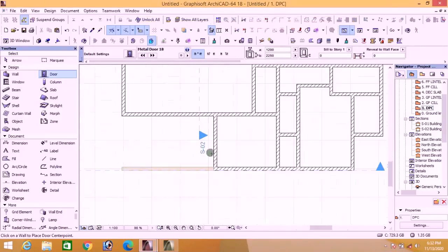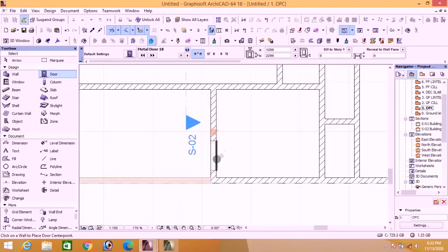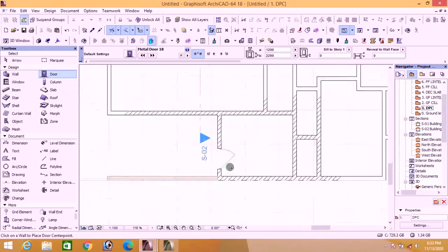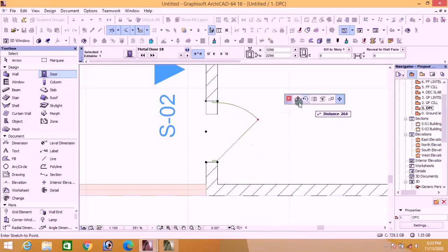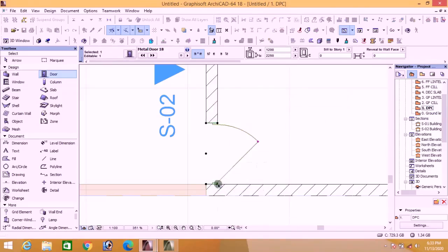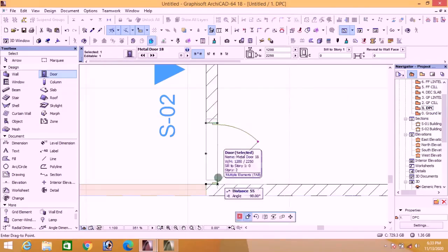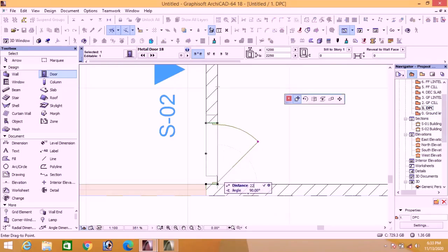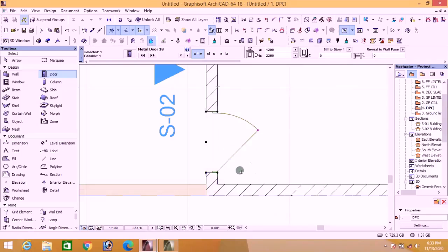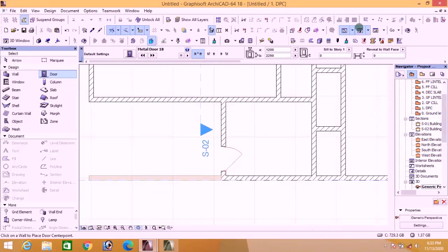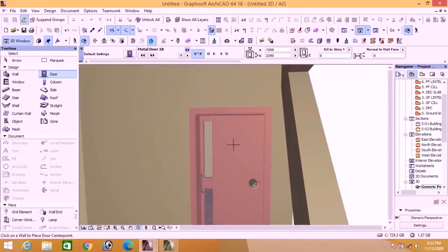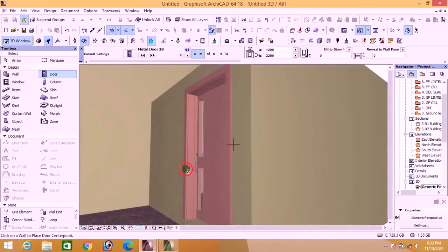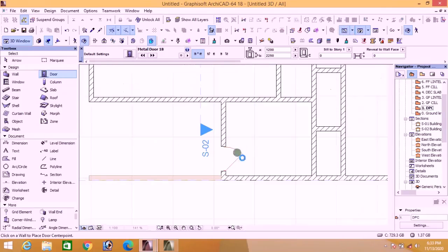That is the door that leads into the ante room. Now you can do adjustment on this door by highlighting the door. Move it to this corner. If you want it to start from this corner, but it's not good to start from this corner, give it offset like 250, 225. That's the position. If you check it in 3D, this is what it looks like in 3D. Can you see the door? Well positioned.